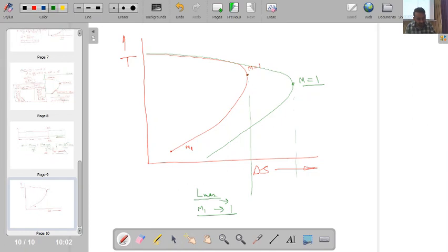Now when you have taken that new curve, your length is greater than Lmax, and you are reaching from the m1 condition to sonic. Okay, so in this situation we will experience that the inlet condition gets modified. Here you can see this was the initial inlet condition, now this is our inlet condition. Okay, and this will get adjusted to some new mass flow rate.